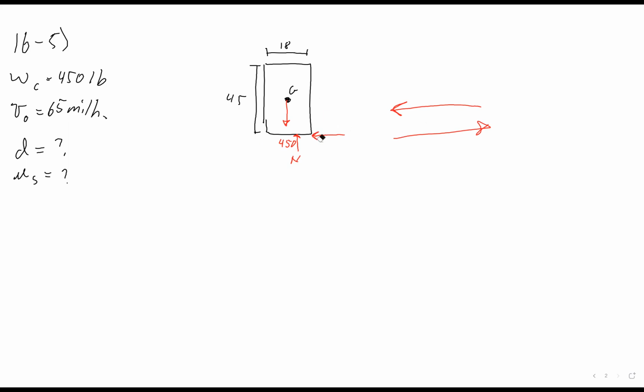Therefore, the friction is the thing stopping the crate, the friction between the crate and the truck. So the friction has to be pointing to the left in order to be slowing the crate down that we have been told is moving to the right. Okay, so we are pretty confident that we are going to get a positive number if we draw the arrow to the left. That also means, and this is not quite as vital, but then there's an acceleration in the x also to the left.